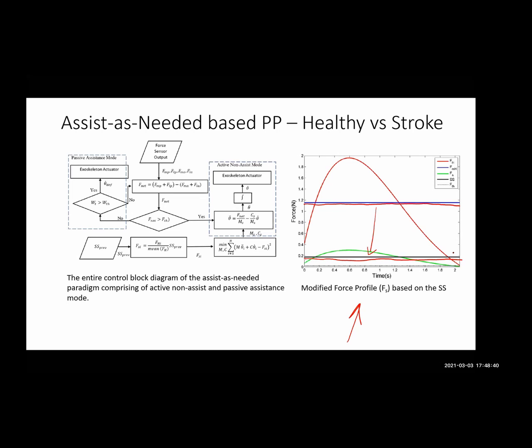So after the first few days, you have to change that M and K, essentially make it higher, put larger values of M and K so that it makes the task more difficult. In the video I showed today, I showed that there's something called stiffness and stiffness rate. By playing with the stiffness, you can make the task harder or easier, and that is exactly what we are doing here. So this is providing assist as needed.